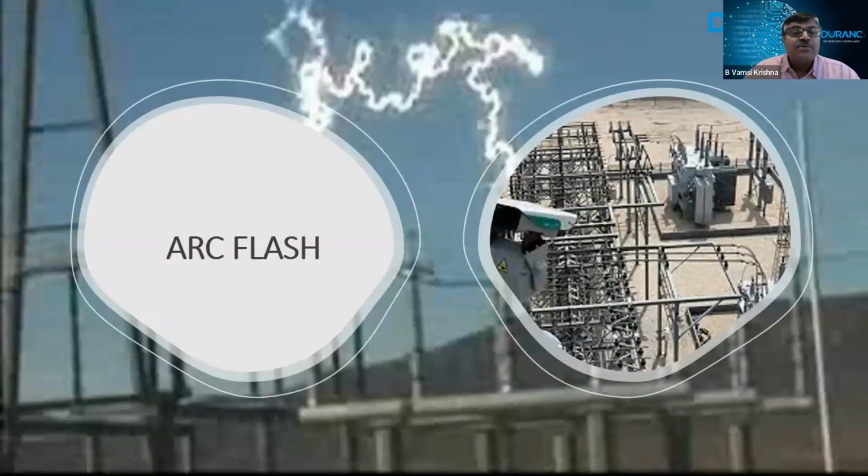Another one that we briefly touched upon is arc flashes. The video analytics can continuously monitor for anomalies in the electrical equipment and environmental conditions, such as sudden spikes in temperature or irregular electrical discharges, which are indicative of an impending arc flash. When these anomalies are detected, the system can trigger immediate alerts, allowing the operators to respond swiftly by isolating the affected equipment, de-energizing the circuit, or activating fire suppression systems.